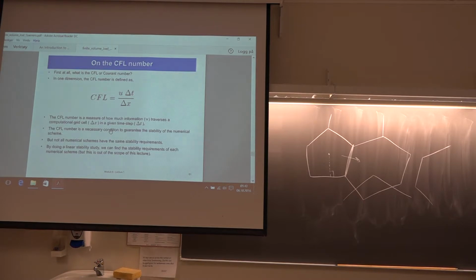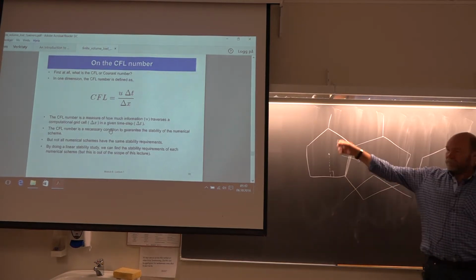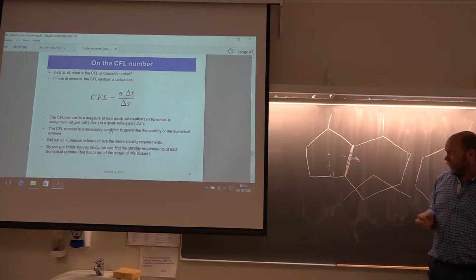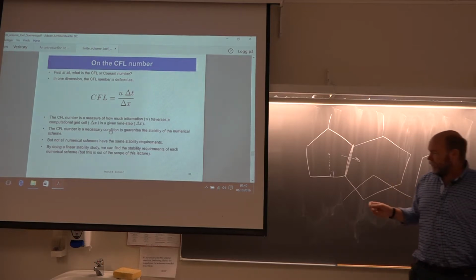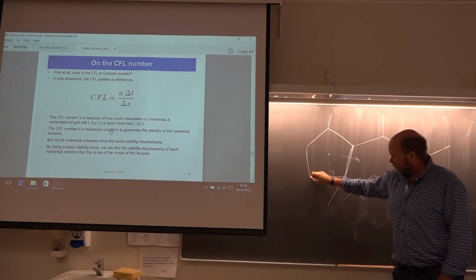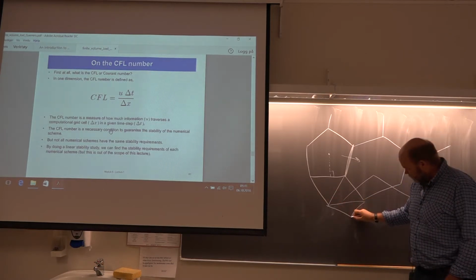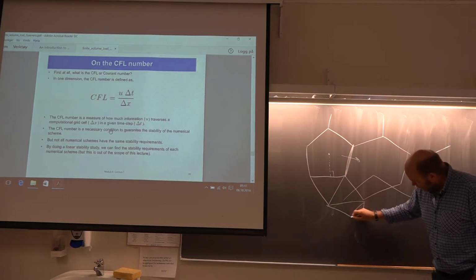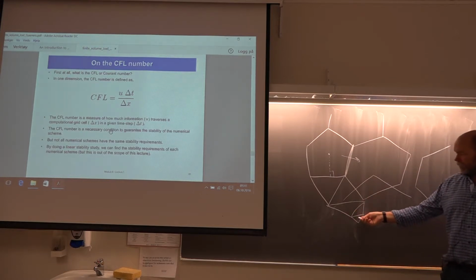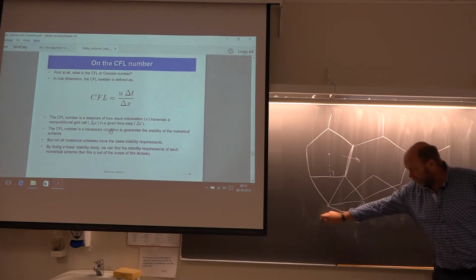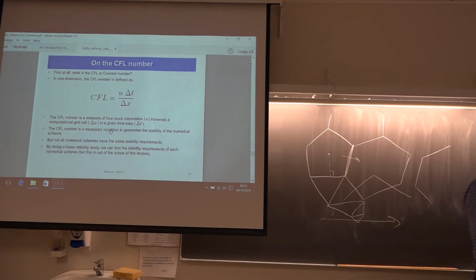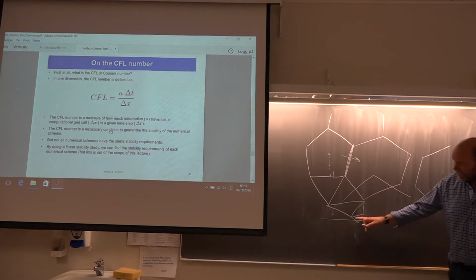And that will be regardless of cell. So if you have, say, a very small cell somewhere, and then we go all the way down here. So we have a very tiny little cell down here. And this is in a location where you have a very large velocity, then you're in trouble, of course. You are not allowed to travel longer than 1 delta x over one single time step.